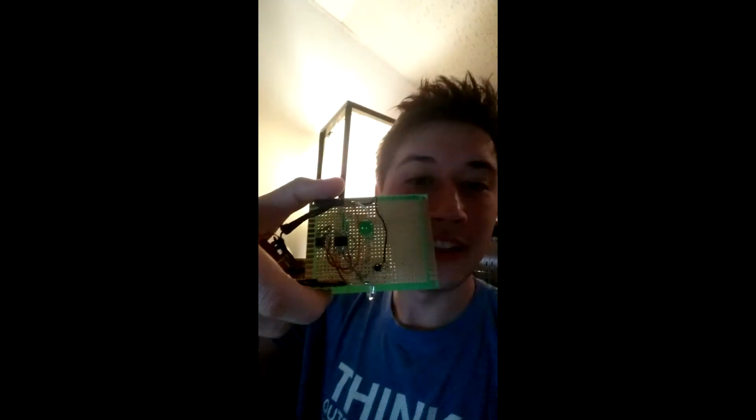I am here again with the IR transmitter and receiver. So last time we had the photo transistor just getting this signal, and it was coming through with a nice 10 kilohertz frequency, except one of our problems was it was a very slopey signal, meaning it just didn't look right. You know, data is supposed to have perfect edges, up, down, perfect step functions, they're called.